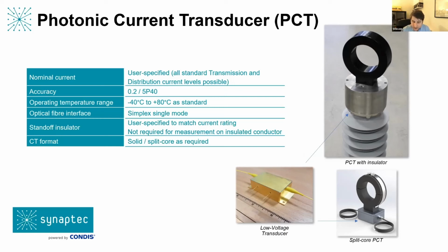But as you say, in this case with StatNet, we did do that extra step where we built a phasor-based differential busbar protection scheme within the same device that we provide. That's an option for a super fast-acting approach where you can act on the measurements immediately as they're generated, rather than sending them out via the process bus. But probably the common case would be to share that information with other devices in the substation rather than integrating the protection. It's a very flexible approach, so both can be done.